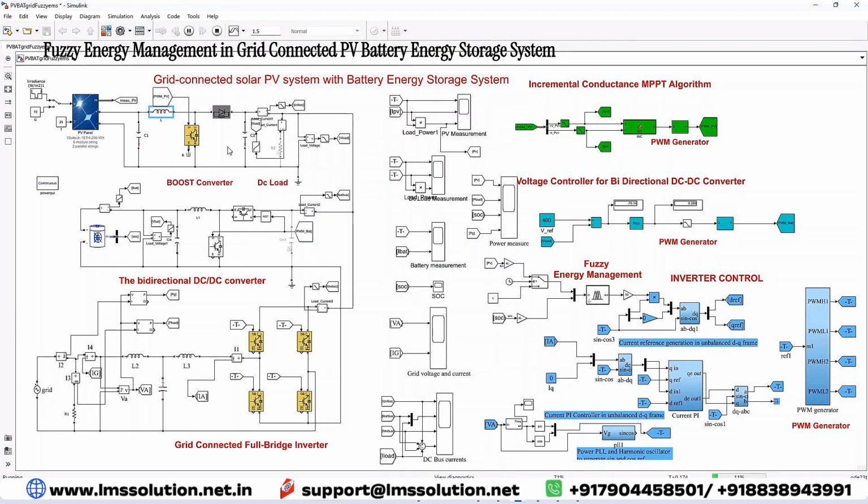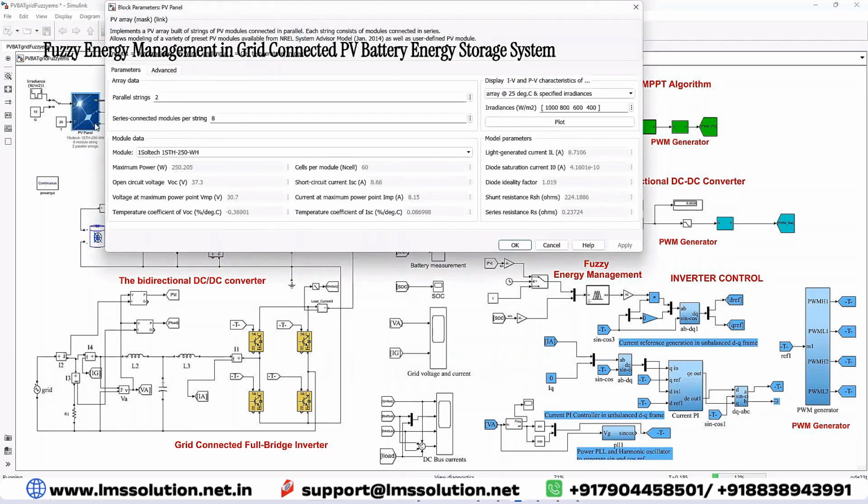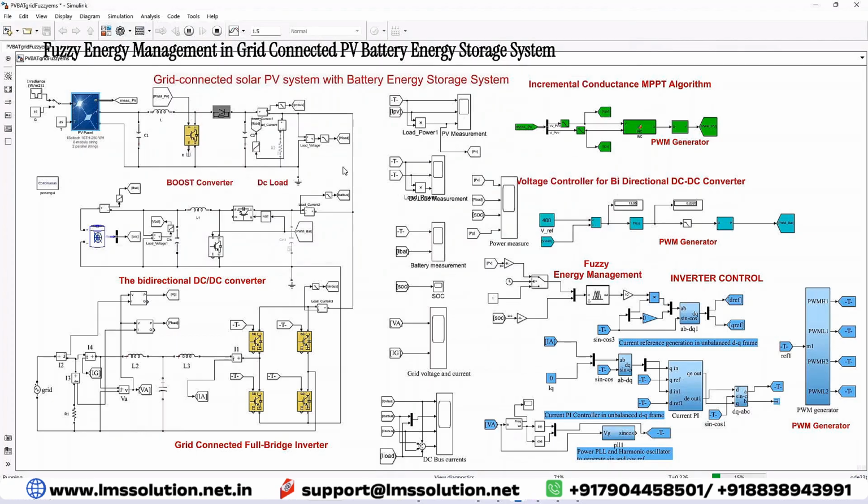This L is the receiver. This is going to be designed based upon the voltage. Single panel voltage is 30.7, and a total of 8 panels are connected in series. We have to take 8 into 30.7. And then here the voltage requirement will be 400, so the input power will be 4000. Based upon that routine, you have to design.